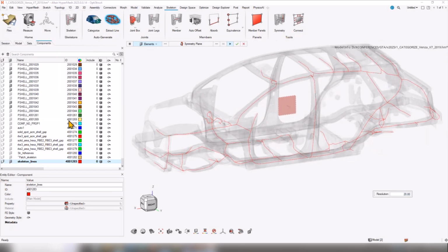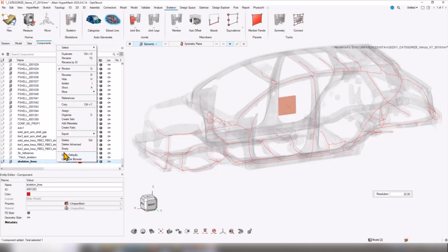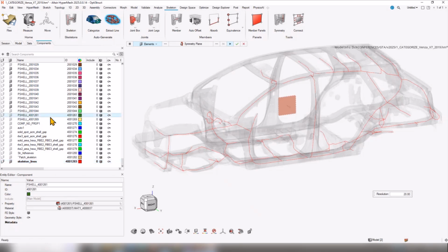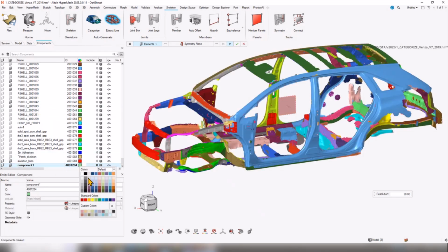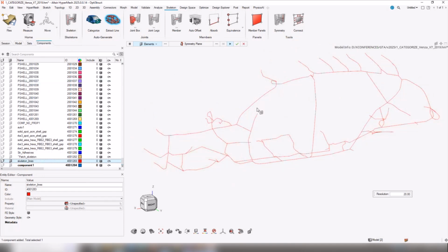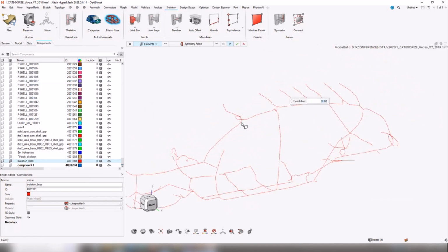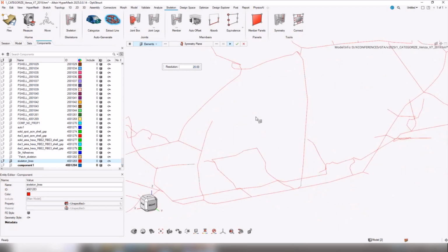I'm just going to make sure that my geometry is created. Okay, so I'm going to go to create, and I'm just going to create that as blue for now. I'm just going to go to isolate that. Now you need to make sure, obviously, that this is going to be in relation to the structure. You can't have these midlines poking out through the structure, otherwise, well, that's not where the load path is going. So you do need to be relatively careful with what you're doing here.